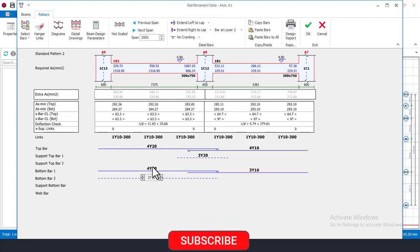So right now, let me try to reduce this now to Y16 and see if that's okay. No, it is failing, so I can choose to increase this again to 3. Let me see. I think that's okay, yeah. But because of the length of the beam, I can choose to make it Y20 and then come here and up to 2. That's fine. So right now, it's now okay for this. Because of the length of the beam, that's why I'm using 4Y20.